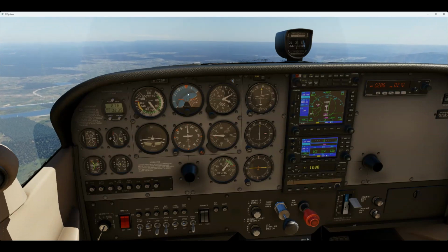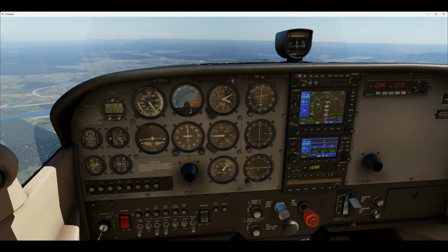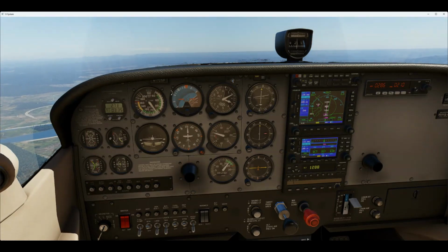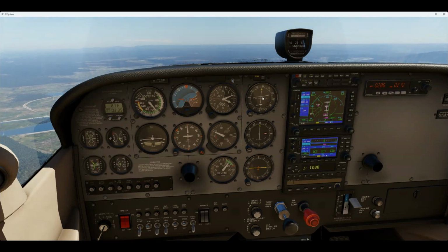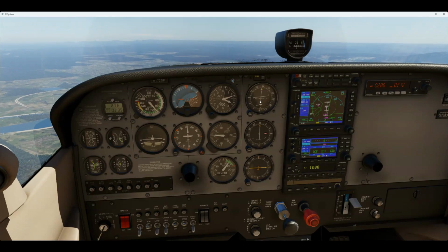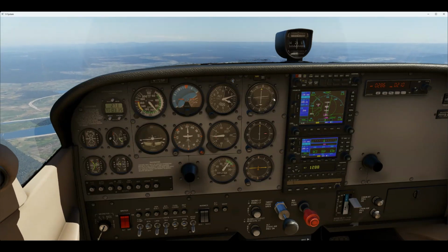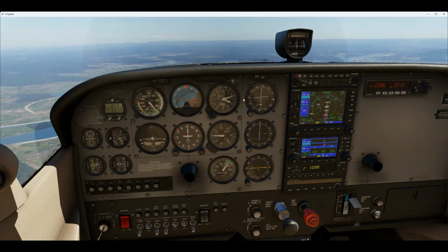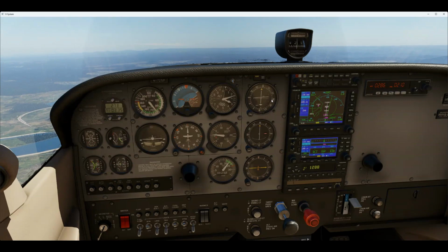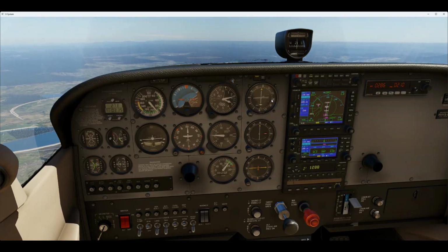We've got this thing here. It's pretty useless because I can't rely on that. So we're just going to wait until the localizer and the ILS, we capture the glide slope. We're good on the localizer. We're tracking that 212. We're just waiting for that glide slope on that top CDI to match. So I'm going to keep my height until that happens. Okay, it's coming in now.